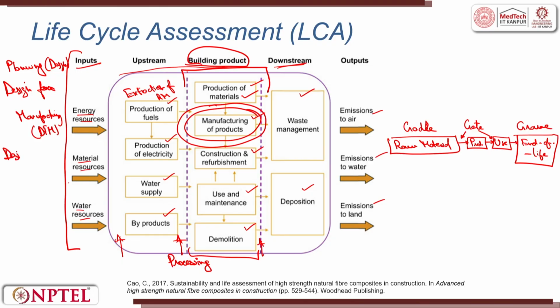We might be using injection molding, we might be using some CNC machines to cut the metal materials. So designs have to be made so that they could be manufactured. Also, when the manufacturing has happened or is going to happen, we also need to see that repair and maintenance should be taken care of. That means the design that you are developing or making should be able to be maintained. So design for maintenance. This is known as DFMN, design for maintenance.